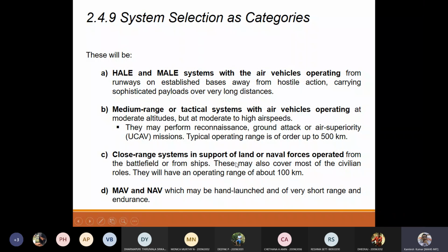This range never suggests aircraft cannot be very large, correct? Range suggests, okay, you can have only a 100 kilometer range, a radius of action. So that is the idea here, but aircraft can be larger or smaller. That depends on the applications. If I have a 100 kilometer range requirement and a 1000 kg type of payload requirement, of course I should have maximum takeoff weight type of aircraft available, which can fly 100 kilometers.